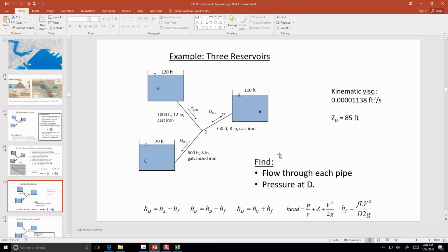No, I don't think so. Conceivably, something like that maybe could happen depending on the diameter of pipe CD, but if there's negative pressures in the pipe anywhere, that won't make our results invalid. We could do a drawing of the hydraulic grade line, and even if the hydraulic grade line is below the physical elevation of the pipe, the energy solution is still going to be valid.